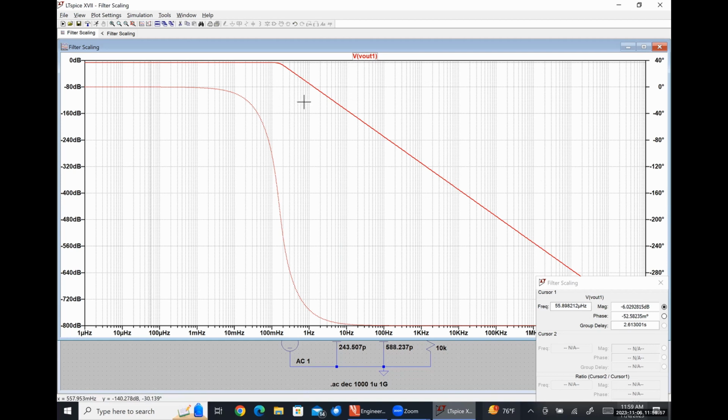So I'm going to bring this over until it looks to be about -9. Like I said, somewhere in the ballpark of 159 millihertz. That's just 1 over 2 pi, no fancy magic there. This was designed for 1 radian per second. Let's see that we have a drop of 3 decibels at effectively 1 radian per second.